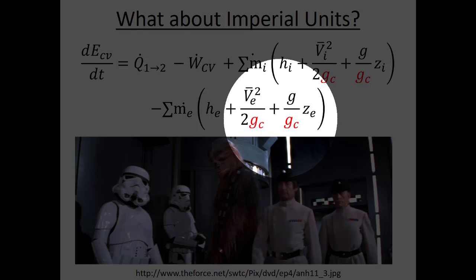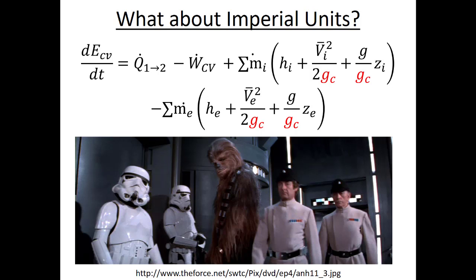And you might not be trying to remember this, but maybe it'll get burned into your memory. Or if not, I'm pretty sure it's just on the equation sheet. But I think there's like 775 or 778 foot-pounds per BTU, right? So again, it's kind of close to 1,000, but you still have to do some unit conversion if those terms stick around. So basically, the hair on the back of your neck should probably start to stick up any time you can't neglect kinetic energy or potential energy in the first law equation.